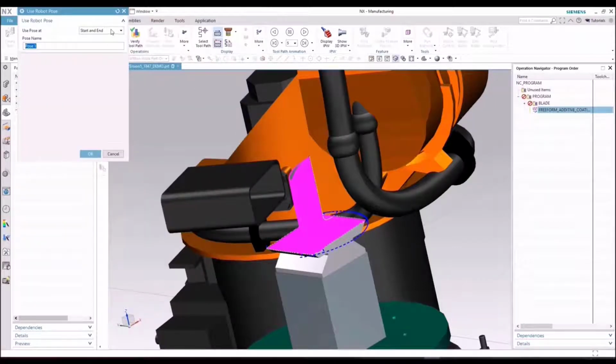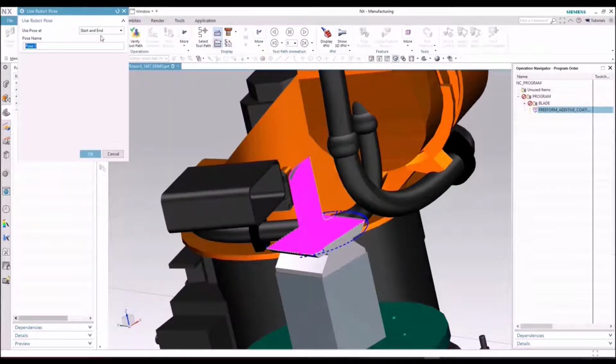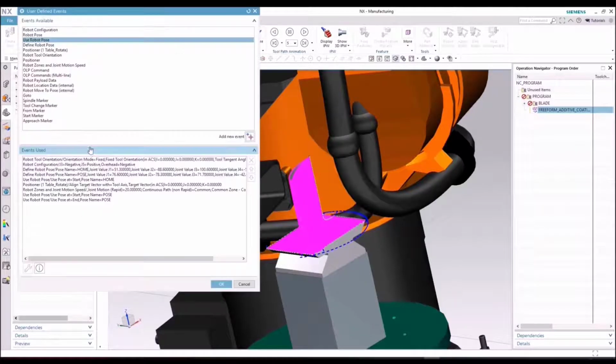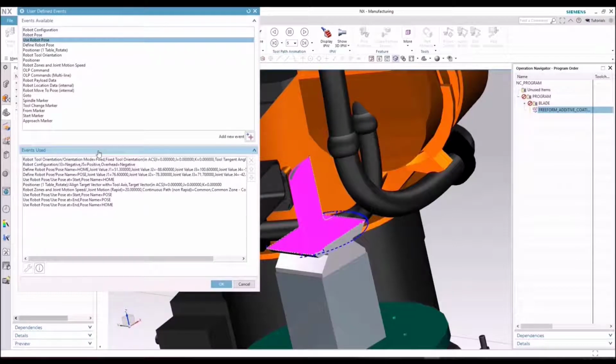Movement instructions to choose from comprise point-to-point movements and linear path movements. Point-to-point commands generate black box direct movements toward the goal position, with the robot choosing the fastest possible way. On the contrary, linear path movements ensure that the tooltip moves along a straight line, with position deviations within a defined tolerance range anywhere.